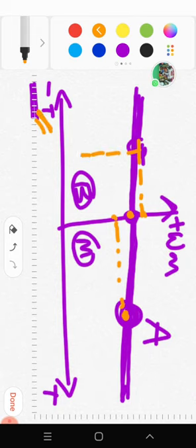So if this is the operating point, then the motor will be running with some higher speed and some negative torque, braking torque. So this is the braking quadrant. How is it possible that the motor runs beyond no load speed? This is possible only when the load drives the motor. There are many loads which have a tendency to accelerate or drive the motor. In that case only there is a possibility that the motor can be running beyond no load speed. That is the braking quadrant.